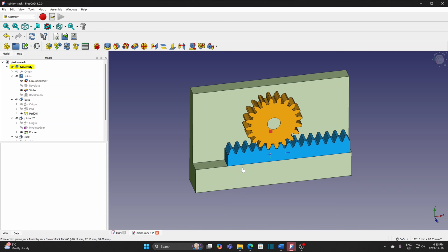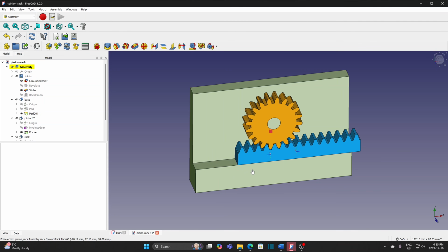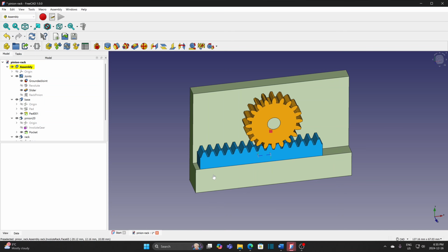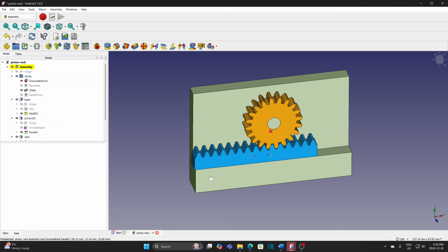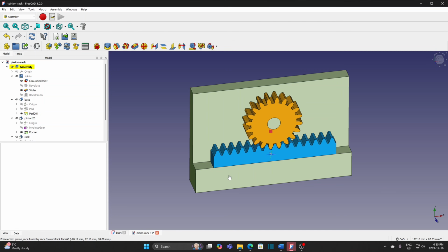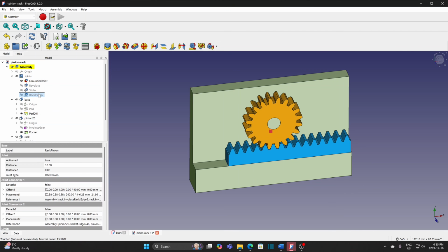Now the gear and the rack mesh. We can also set up the min-max for the slider joint, which controls the range in the pinion and rack joint eventually. In some cases, the rotation direction may be wrong. Open the data window of the pinion and rack joint, change the distance to minus, that could reverse the direction. However, I would prefer to delete the joint and redo it again. And usually, it would be fine.